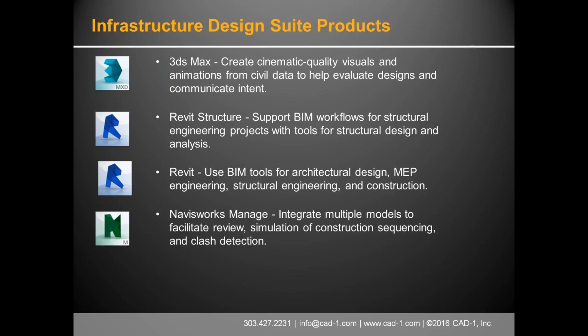And then Navisworks Manage. So it's similar to the Simulate version that we had mentioned, but there is a little bit more capability, such as clash detection, which is widely used for determining issues before anything's even built. Any good examples, Brian, you could provide on Navisworks Manage versus the Simulate? Sure. So Navisworks Manage does clash detection. That's really the big deal with the Navisworks Manage.